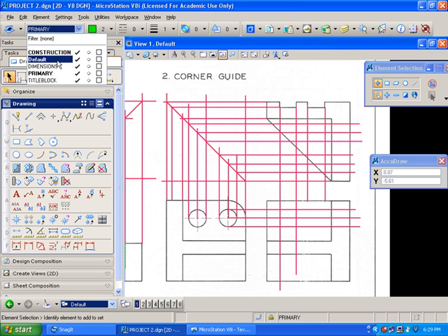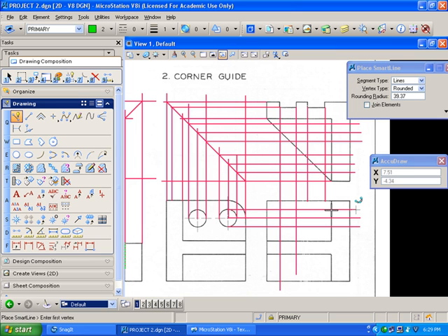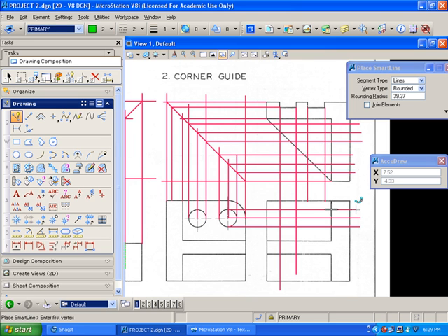Okay, so now I'm back. We get the primary lines. We're going to go to green and start putting these primary lines in their proper location. We're going to see a hidden line where this hole goes through right here and right here. We're also going to see these holes here and approximately here. This is both edges of that round hole going through. We'll trim these out a little bit after we turn off the construction lines.